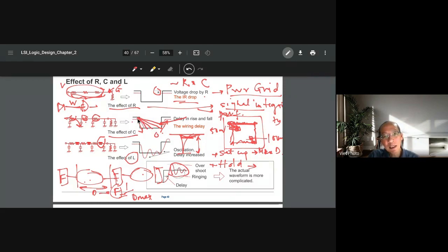So you can see that if the resistance is too much, along with high capacitance, then it cannot discharge enough to get to 0, and then you go up again. The consequence is that this is not really a signal from 0 to 1, but something in the middle, which fails the requirement for the signal voltage.